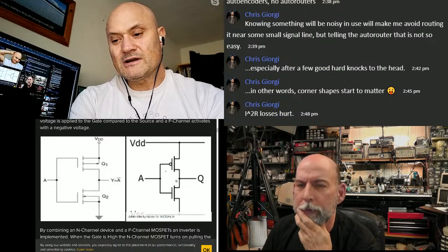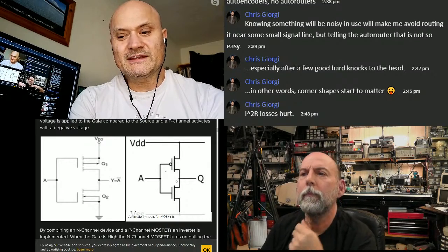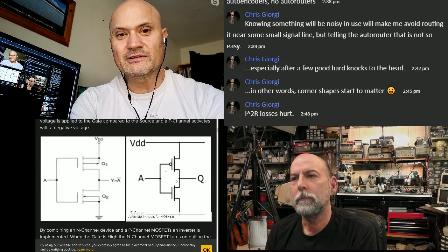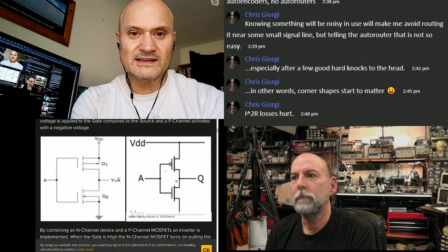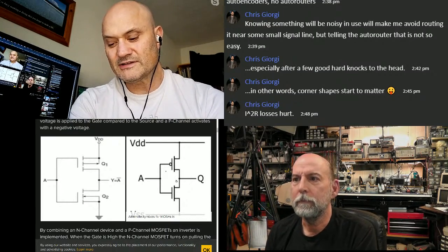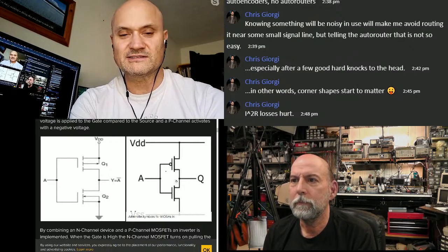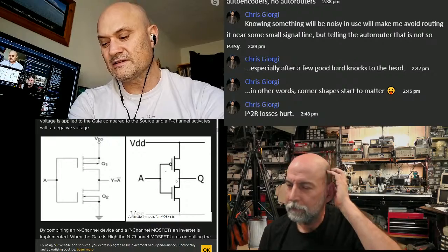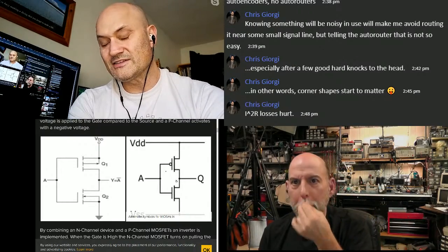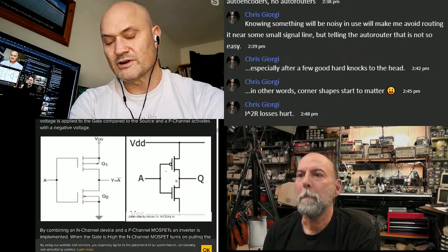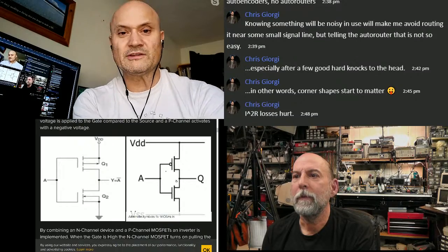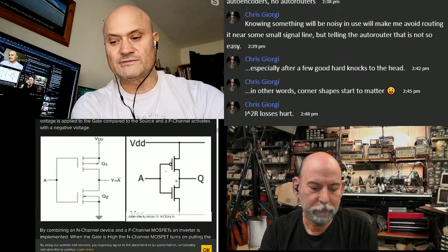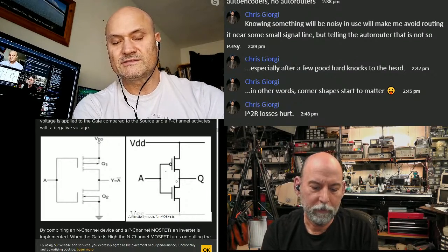Well, from what I've seen, if the fabricator is actually capable of doing more than 12 layers, because there's a lot of factories out there that wouldn't go beyond, say, 16. They don't have the equipment, but the ones that do usually have pretty high-end, good modern equipment and good processes. And so those high layer count boards become very stable.